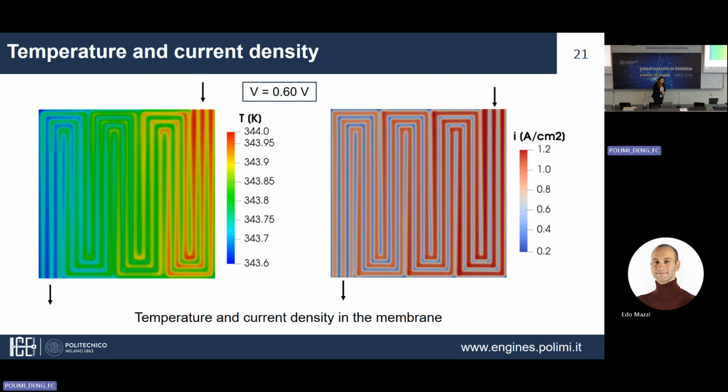And this could be pretty interesting in case of analysis of degradation mechanisms, because, as I said at the beginning of the presentation, water management is a fundamental parameter to be taken into consideration, because if we have some regions in our fuel cell where water concentration is too low, we can have some local hotspots arising, and so some portion where the temperature increases a lot. And so with this methodology, we could detect the points on the fuel cell where a degradation mechanism could happen.